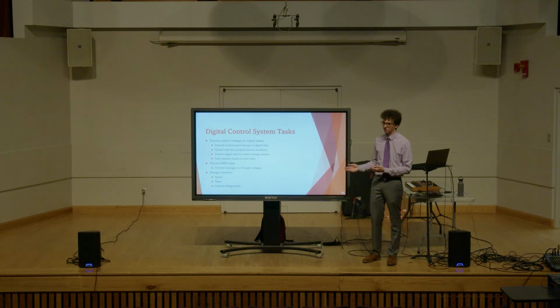Additionally, the digital control system should be able to process MIDI messages. So it should read MIDI coming in, it should parse what it is, and then convert those input messages into control voltages for, say, the oscillator pitch and the envelope gate. And then it should also be sending MIDI messages out depending on the notes that it is getting, if you want to send any MIDI information to a throughput, or if you've implemented a clock or a tempo inside the system, it should spit out that information on an output.